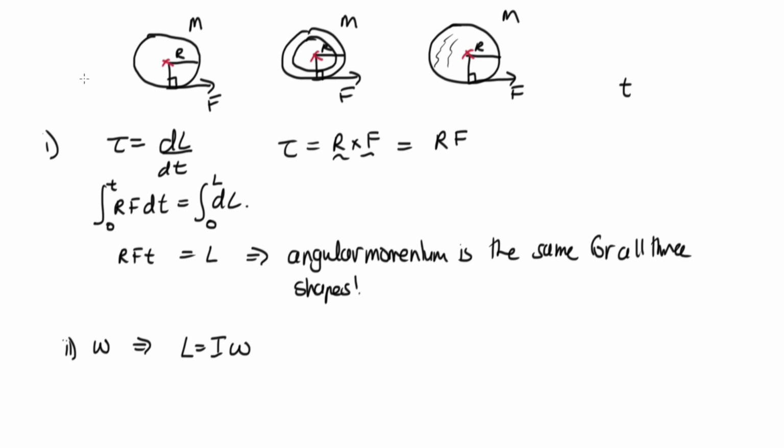So they've all got the same mass. The one with the smallest moment of inertia is going to be the one which has the most mass closest to the center. So that's going to be the sphere, as it has more mass, it's wider at its center than it is at the edge. So we've got that the moment of inertia of the sphere is less than the moment of inertia of the disc. And then the hoop's got the largest because all the mass on the hoop is concentrated near the outer edge.